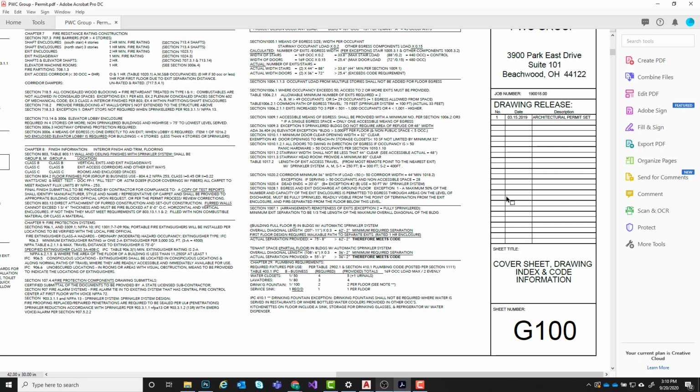As you go through a real project, you're going to have to do revisions, most likely. So you'll send it out, and then they'll start working on it, and it's going to be going back and forth between you and the contractors, but there might be things in the design that have to change. So they will give you feedback, and then you'll go back and make those revisions, create a new set of drawings, and then put that back out. Every time you create a revision set, you have to indicate that here in the drawing release by saying what revision number it is, the date, and then in the descriptions, you're going to note a brief description of the revisions that are within the new version of the drawing set.